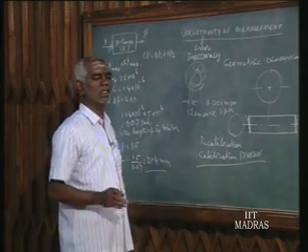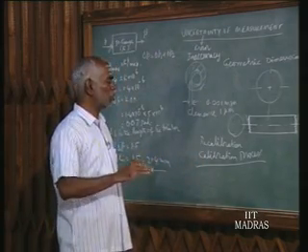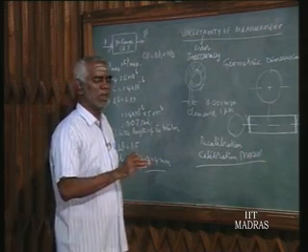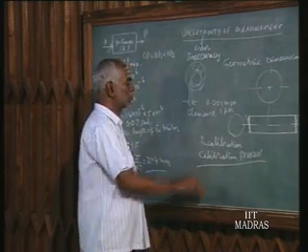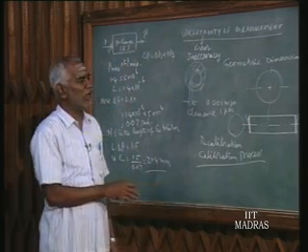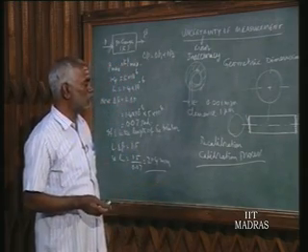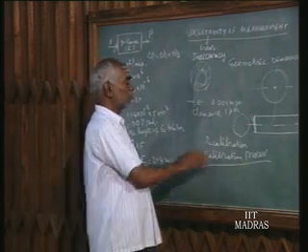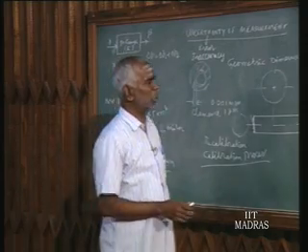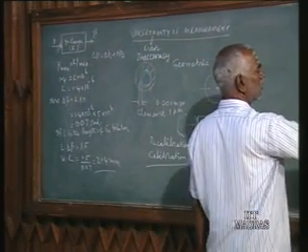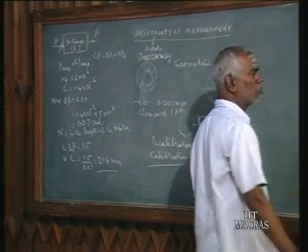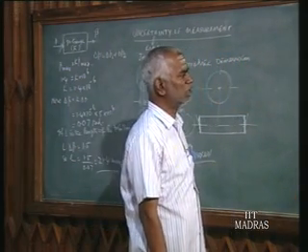So temperature may be 20 to 40 degrees. Humidity may vary between say 50% to 100%. Like that, atmospheric conditions are specified for any instrument in which it is supposed to be used. For that purpose, let us consider a pressure gauge. This is a standard instrument. This is the instrument which is going to be recalibrated, the instrument under test, under calibration.